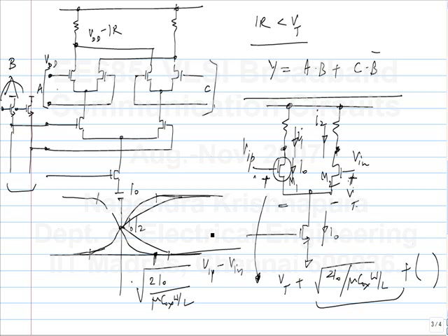The source potential lowers itself when it's in triode or saturation? No, both paths do conduct, right? When the input difference is 0, both are conducting. In fact, it's not a question of source potential lowering itself. The source potential will have to be whatever value is required for the current distribution. The gate voltage determines the source voltage. You are saying what will happen if this voltage lowers? But then, what are you assuming for the gate? They are at a fixed voltage?